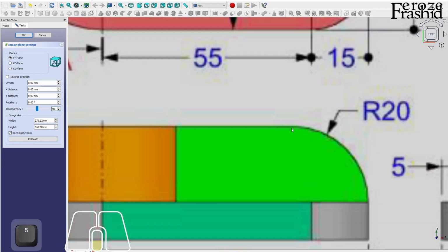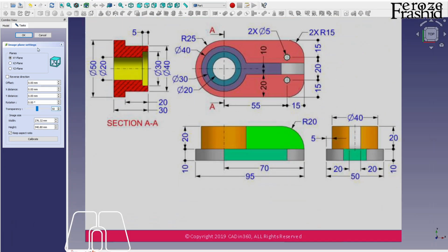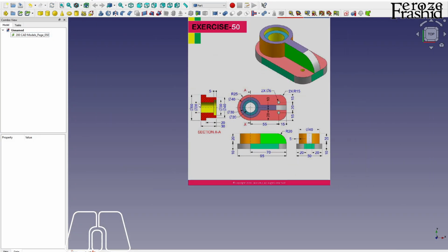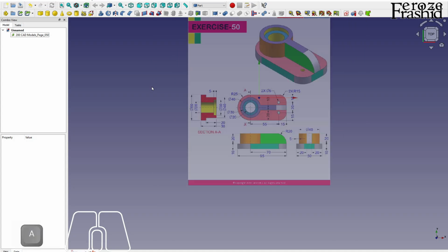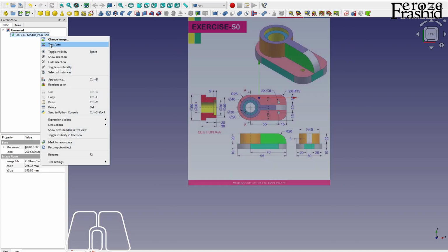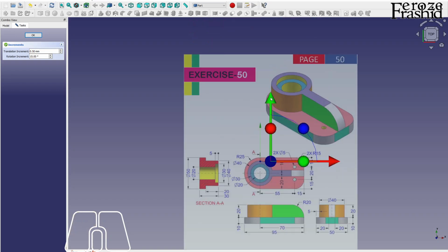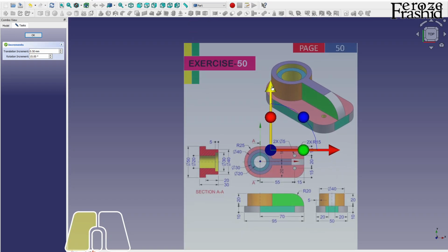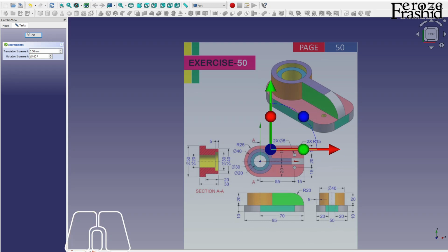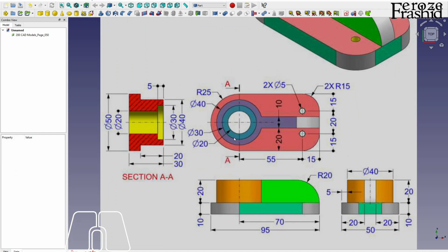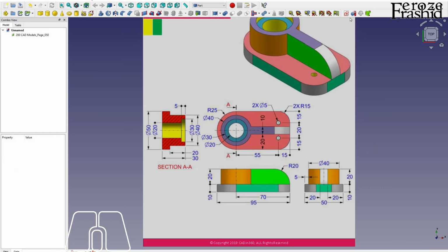Alrighty, I want to keep this image on the XY plane because all my sketches for this object will be on the XY plane. Let me go ahead and relocate the image to match the center of the work center. I am taking the center of the circular hole as my work center. And now I want to get my hands on my first sketch, which will be on the XY plane.